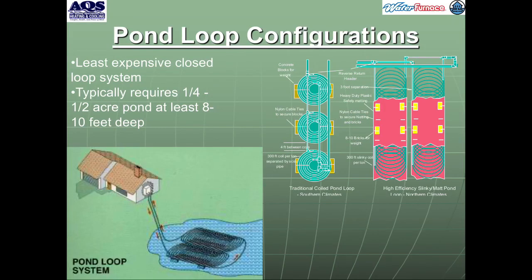So the pond. We can look at this one. This is by far the least expensive, especially if you don't have to dig the pond. But on this particular one, you need to have a pond that's sufficiently large enough and deep enough, so that it does not freeze completely. And that's the one thing that has to happen. So this is again another one of these where a person has to design it properly, and talk to people that have experience designing these things, and that would work pretty well on here.